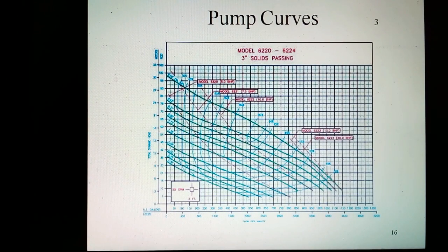The point where the pump operates on its curve is dependent upon the characteristics of the system in which it is operating, commonly called the system head curve, or the relationship between flow and hydraulic losses in the system. This representation is in graphic form, and since friction losses vary in the square of the flow rate, the system curve is parabolic in shape.